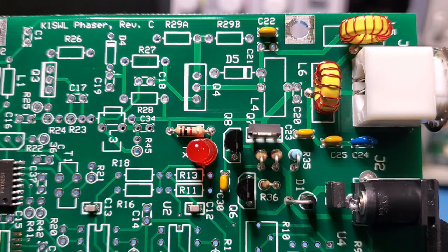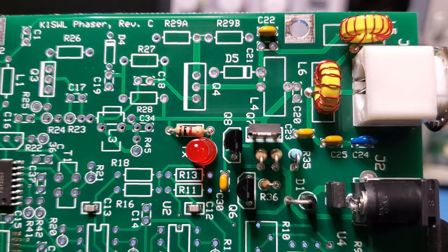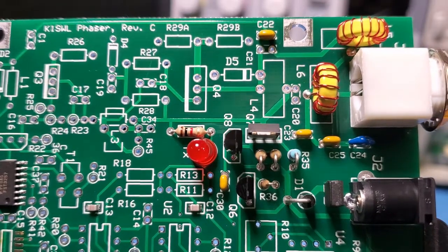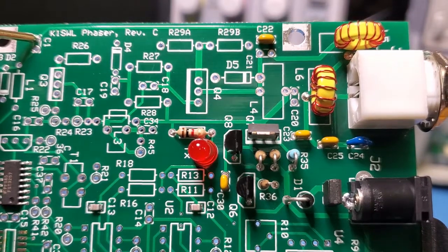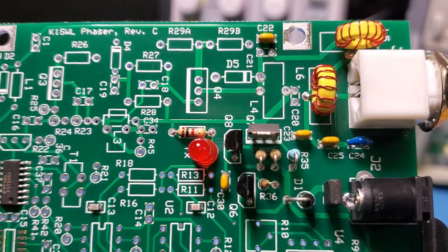So to check that the toroids are correctly installed, I can check conductivity between the center pin of the antenna connector, the BNC, and all the way over here at C1. That just confirms that you've taken the enamel off the wire correctly, and you've soldered the toroids in correctly. It doesn't confirm the value of the capacitors, of course. Sometimes I go ahead and check that with a spectrum analyzer, but I won't do that in this case. I'll trust the designers have it right.